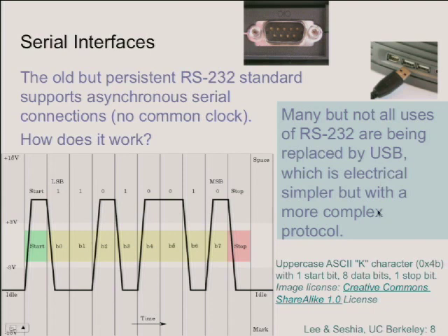So how you use USB, how arbitration is done: you can hang a bunch of devices off the same USB line, so arbitration becomes an issue on a USB line. How all that is done is considerably more complicated than RS-232. RS-232 is simple point-to-point. Only 2 devices, 1 sender, 1 receiver. The sender sends out on the send line, the receiver receives on the receive line. If you get them backwards, no communication happens, right?